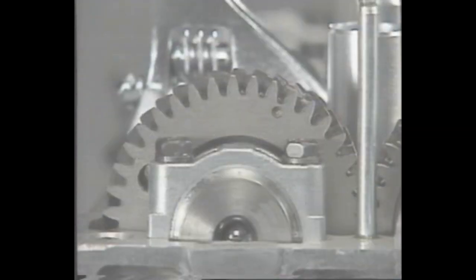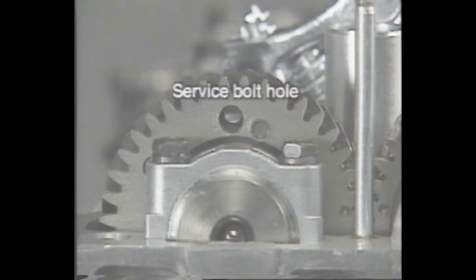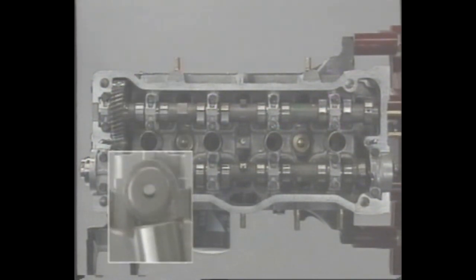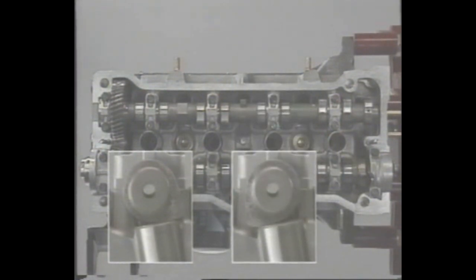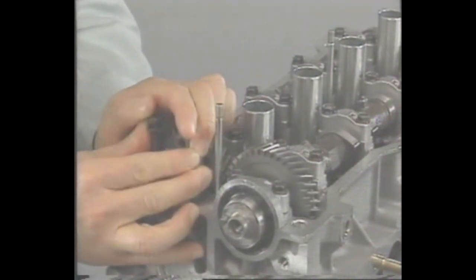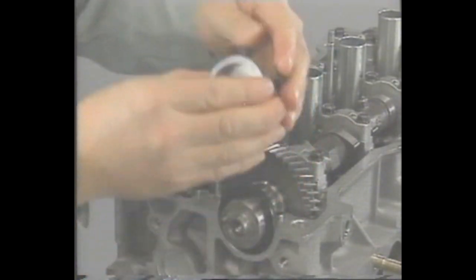Turn the intake camshaft until the service bolt hole comes to the top. With the service bolt hole in this position, the number 1 and number 3 cylinder cam lobes will push their valve lifters evenly, minimizing the load from the valve. Then remove the number 1 bearing caps of the intake and exhaust camshafts and remove the oil seal.